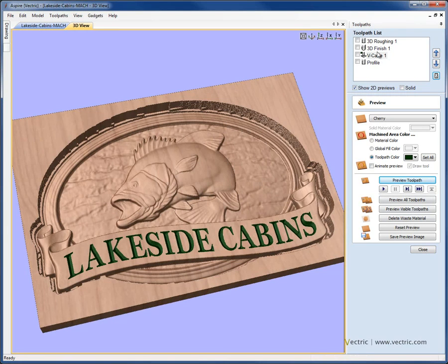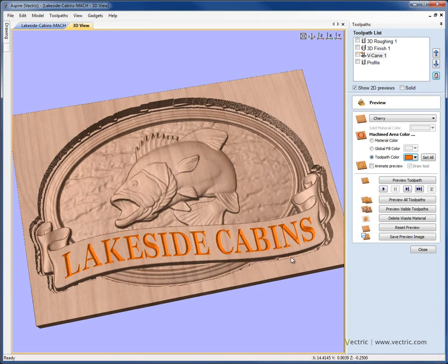And I can see up in the toolpath list that it's put a small square which is also the color that we've selected there. It's a little difficult to see that's the green, but if I selected something like the orange color, we can easily see that square displayed up in the toolpath list. So that's another option for customizing how my part will look once I've run the preview over it.